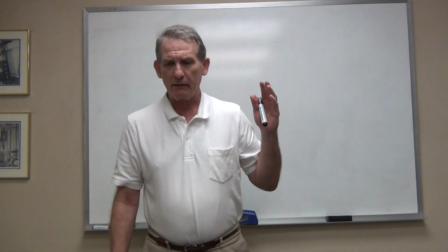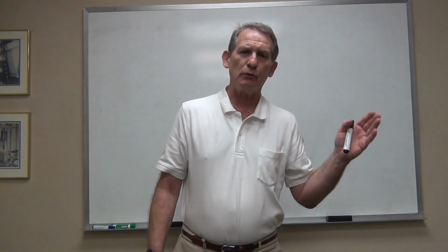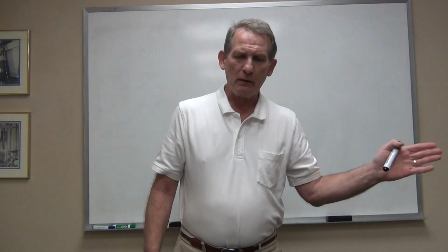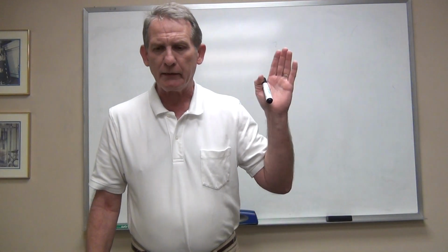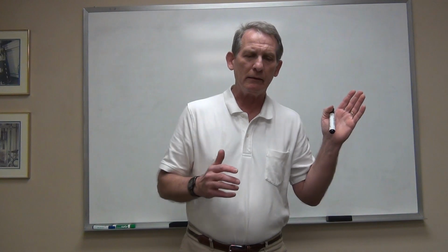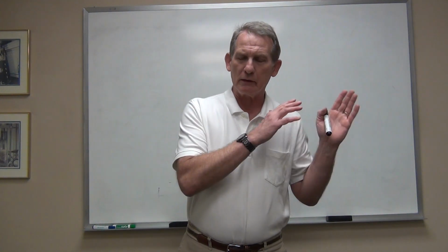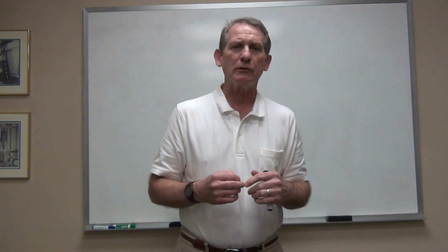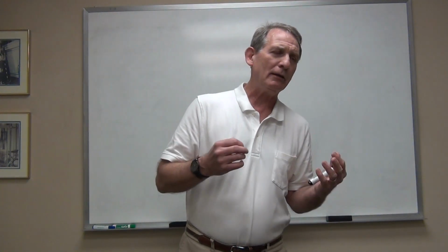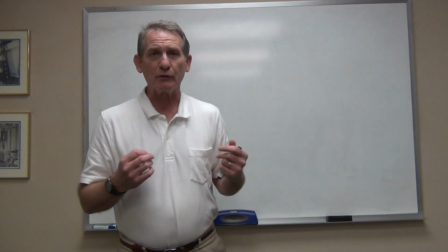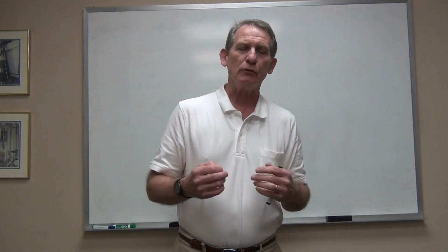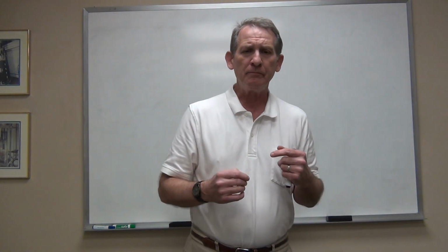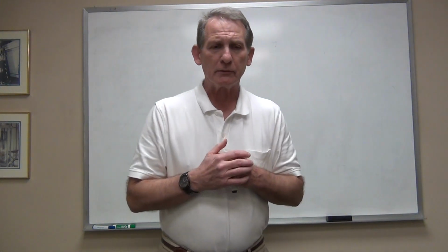When I said that an orientation control is going to establish a tolerance zone of orientation, it is always going to be comparing that feature and its orientation to some other feature. The other feature then has to be considered a datum. What is a datum? A datum is a reference point. It's something that you use to measure from or measure in comparison to, and that's really all it is.